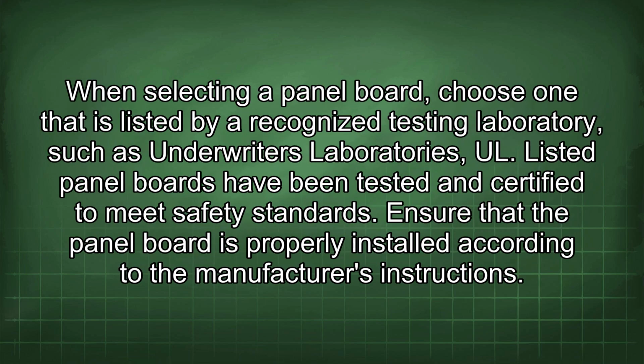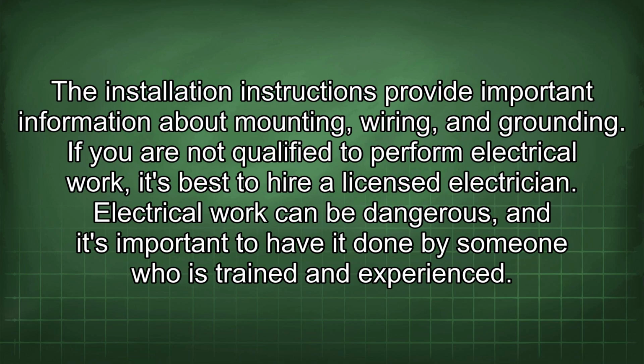When selecting a panel board, choose one that is listed by a recognized testing laboratory, such as Underwriters Laboratories. All listed panel boards have been tested and certified to meet safety standards. Ensure that the panel board is properly installed according to the manufacturer's instructions. The installation instructions provide important information about mounting, wiring, and grounding.